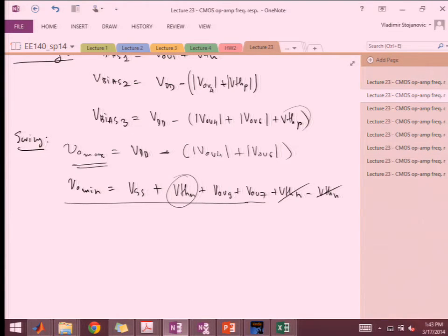When we did the first cascode, we exactly got this issue that it's not just overdrives adding up at the output, but also this annoying threshold voltage, right? And so we did something with the cascode to be able to kind of get around that. That's how you did the biasing, right? To be able to do multiple VOVs. Yes, and that then became part of some other topology that we talked about. Such cascode. That's where you have the level shifting device that eats up another VTH. And yeah, we'll do a short example of that, but later. But this is just kind of where things are.